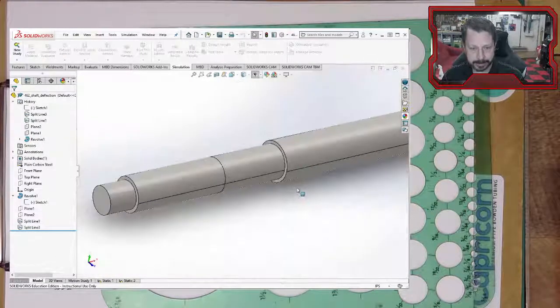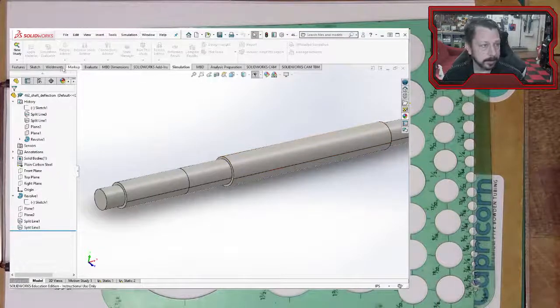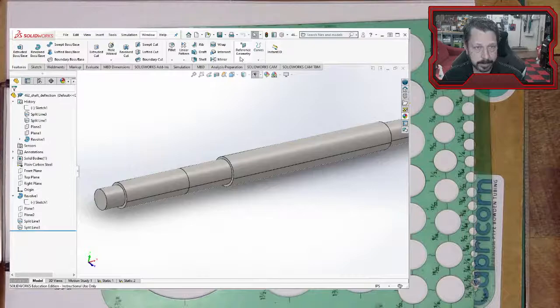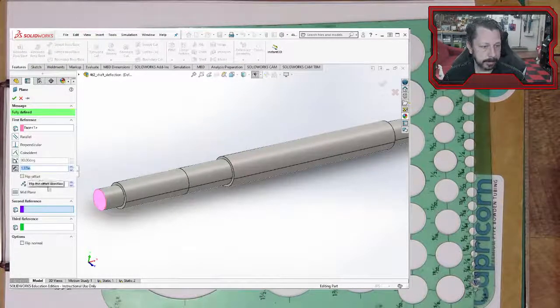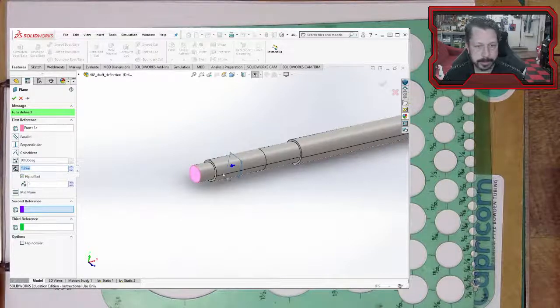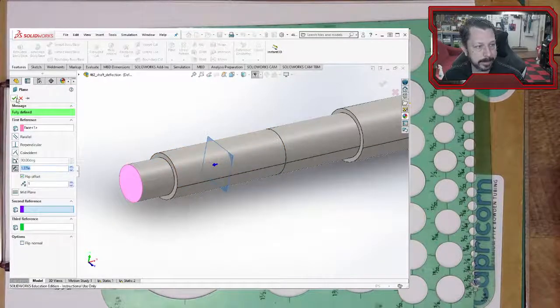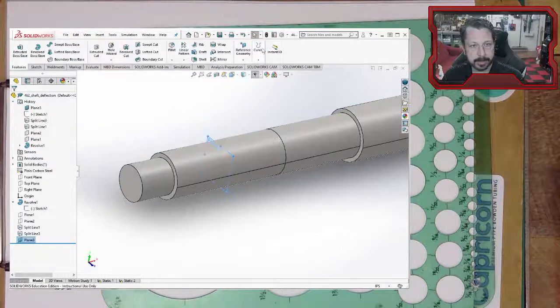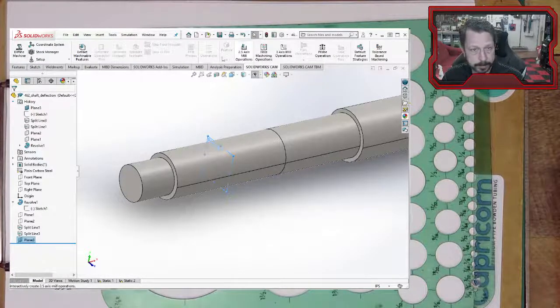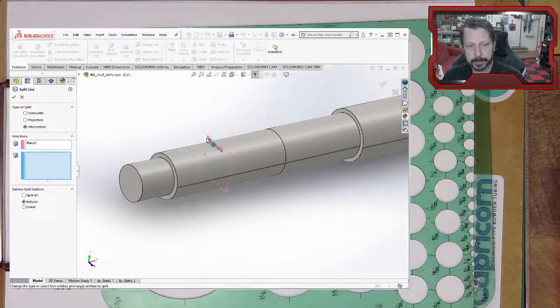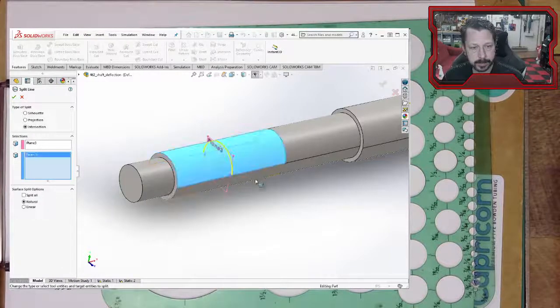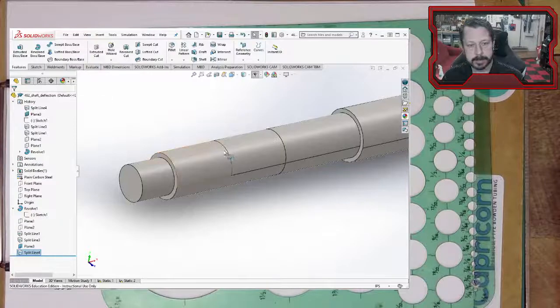And I created the split lines in SolidWorks with a reference frame. So if I go to features, let's just make one real quick. Reference geometry, a plane, and we'll make it parallel to this, and we'll make it, where did it put it? Put it over there. Let's flip it the other way. So there, maybe if I wanted a split line right there, I could generate a plane on that surface, and then I could do curves and split line. Whoops, I skipped off of it. Curves and split line. And then you select, in the pink box, what's going to do the cutting. And in the blue box, you select what's going to be cut. And then you check, and then I've got that split line right there.